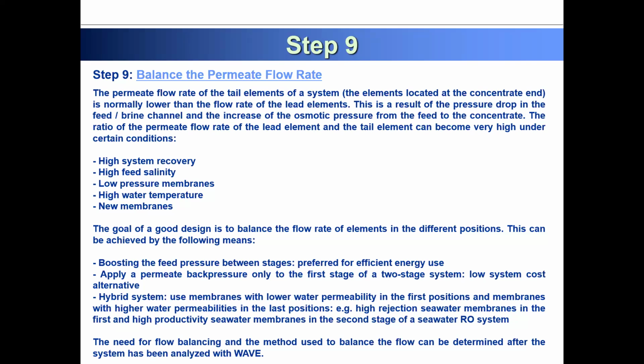The goal of a good design is to balance the flow rate of the elements in the different positions. So this can be achieved by the following means. Boosting the feed pressure between stages. So if you give a consistent pressure, you will produce a consistent permeate flow.